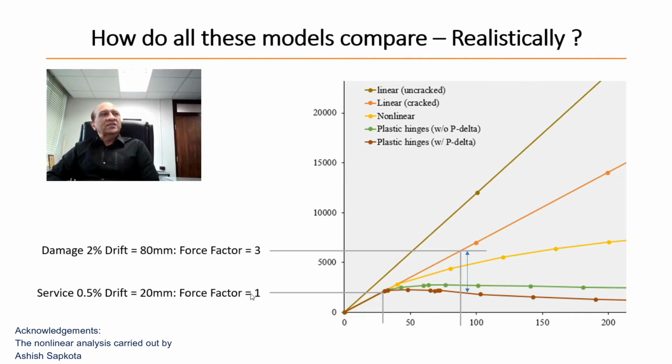When we look at the damage limit or damage consideration for a drift around 2%, which is often considered as the point where seismic design, performance-based design and other things have to be considered. So 2% is a rather large displacement drift limit for frames of this kind.